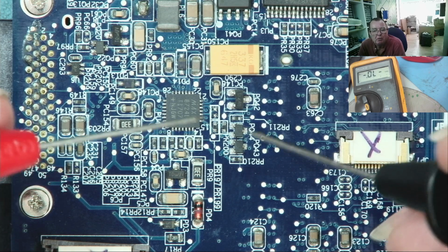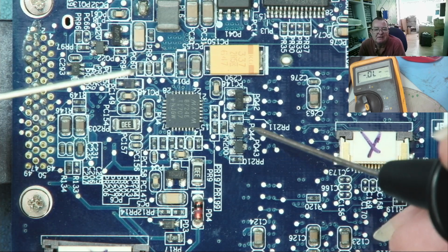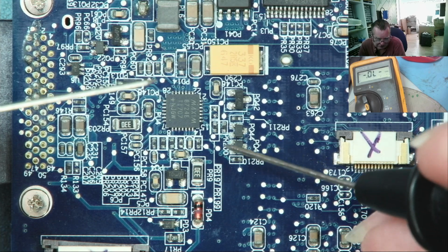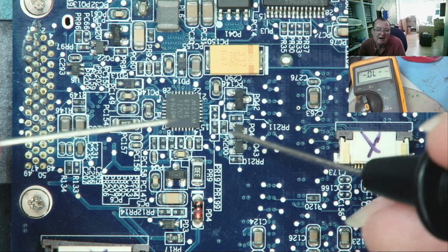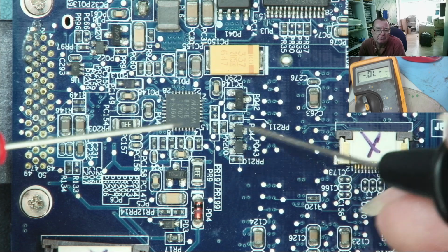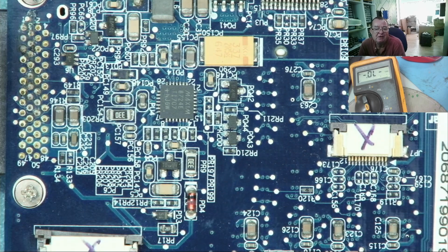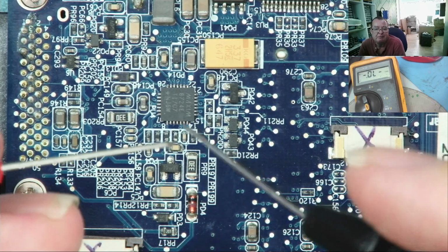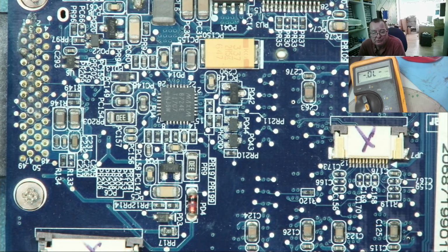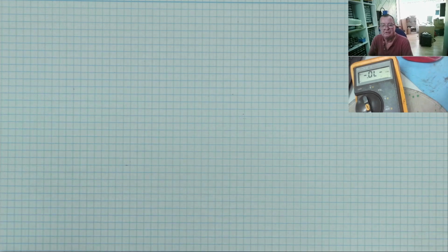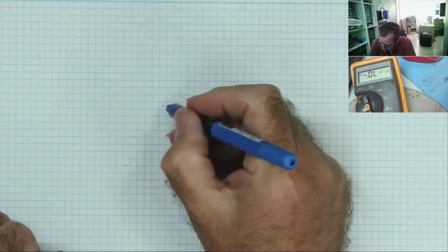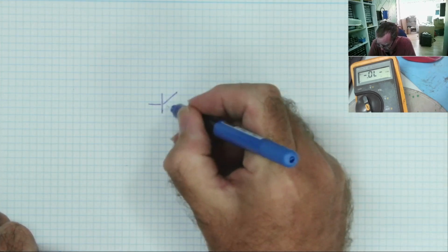And then because you know that on an NPN the collector is a higher voltage than the emitter, you'll know whether that diode you see across collector emitter is reverse biased in normal operation. If it's reverse biased, don't worry about it. If it's forward biased, you need to find out why. And I'll just put that on a piece of paper as well, just to make it a bit clearer. Yes, this is always easier when you draw it. So you'll sometimes find this.